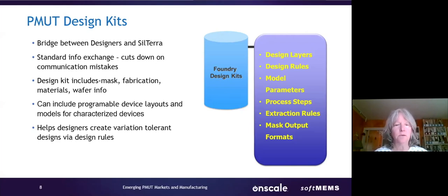So the design kit includes things like mask information, fabrication information, the materials, the wafer information, and in some cases can include programmable device layouts and models for those characterized devices. And in this way, if you use the design kit and you work with SilTerra, you can create a variation tolerant design via the design rules that they give you to produce successful devices. So at this point, I think I've given you some food for thought about what's important in terms of design of PMUTs, and I'll turn it back to Mike and our subsequent talk.